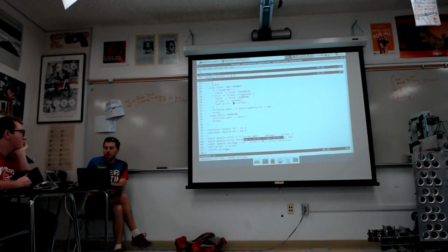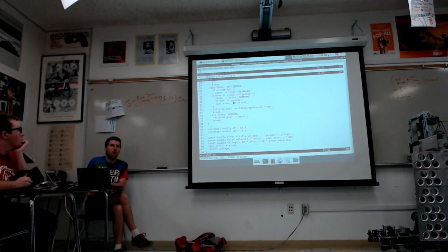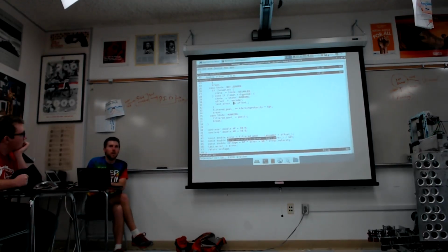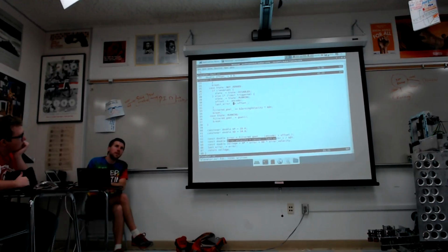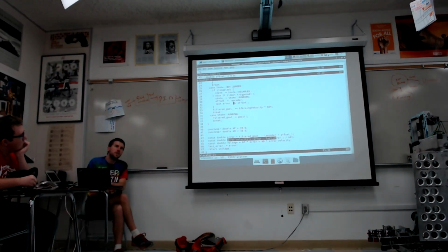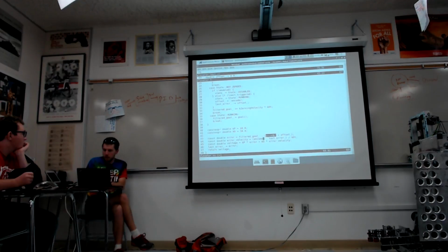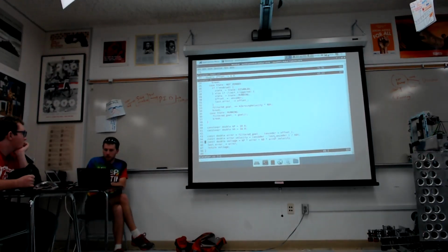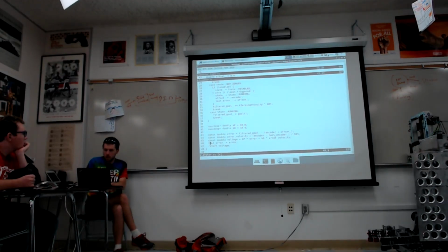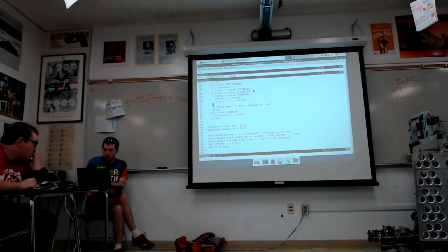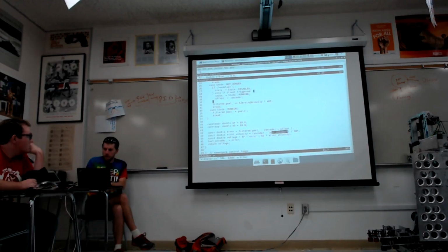Potentially, I like to think what's going on is since we're jumping our goal, there's a large error velocity here, so we might just need to rephrase our D term and ignore the motion. We should set a last error. That might fix it.